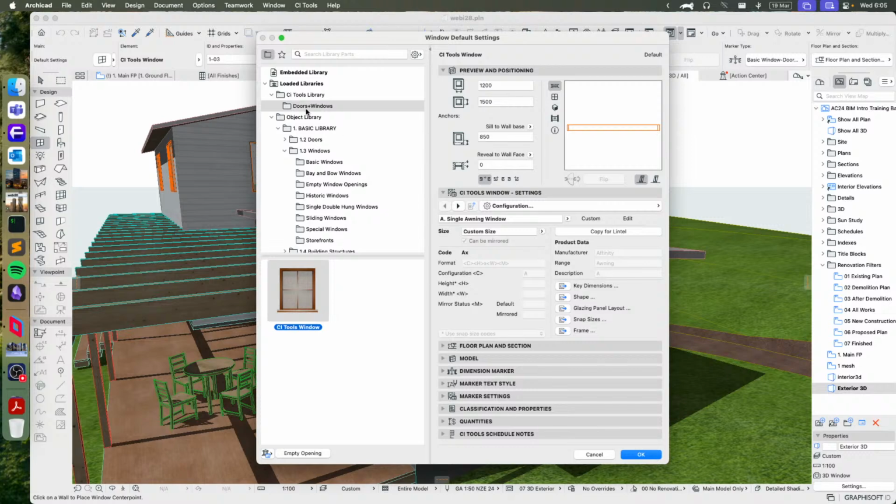So, as I say, with the Doors and Windows tool, the first decision that you have to make with our window tool as to what you want to place is just if you want to use our window tool. This single object will allow you to build a number of different structures and varieties of windows, so you don't have to make that decision as to how many panels there will be or how it will be split up or anything early on. You can make that decision at any point in the process, and you can change your mind at any point in the process as well.